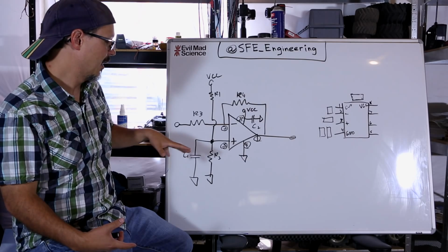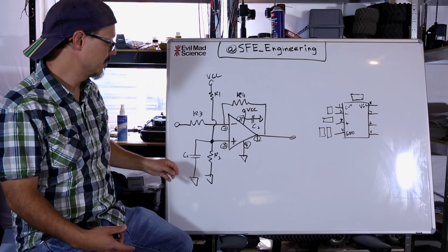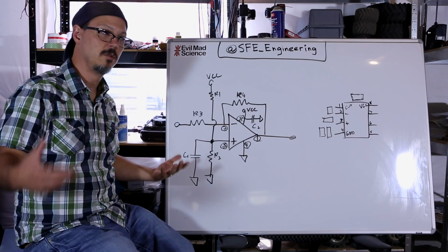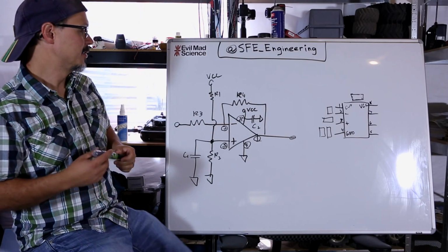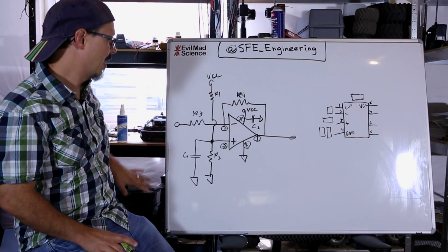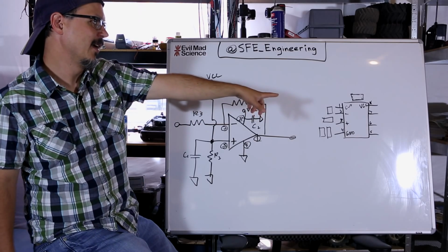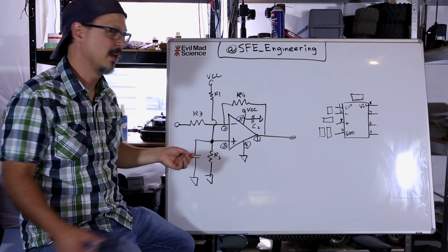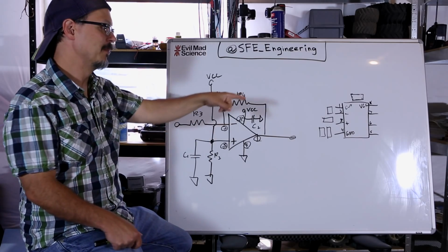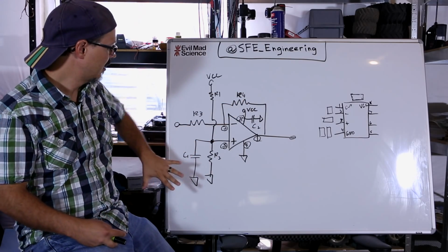So, like I said, the parts that are close to each other electrically, you want them to be close to each other physically on the board, okay? As an example, I drew up a quick op-amp circuit. With this, I drew a SOIC 8 surface mount op-amp part, LM358, 2 op-amps on it. I'm using 1. Here's our schematic.